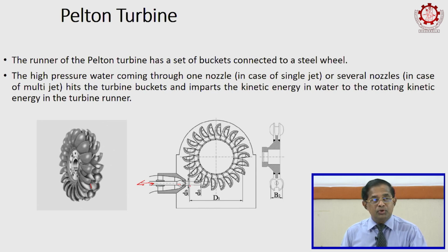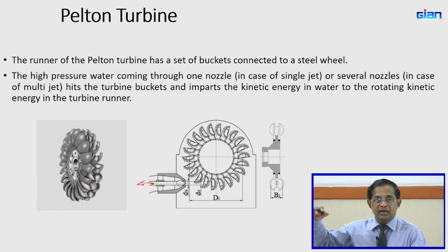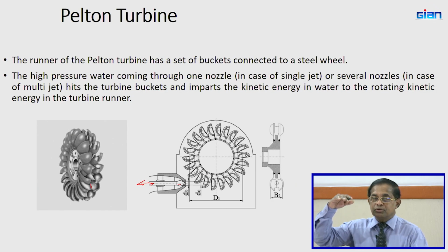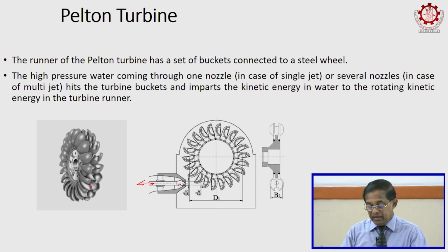That is how it works in a run of river scheme, which we will come to in a later discussion also. In a run of river scheme, the water coming into the project can vary slowly during the day. If rain comes, slowly the flow rate goes up, then the water level at the forebay tank tries to go up, which will be sensed, and the signal will be sent to the needle valve to open a little. Then again the water consumption or flow rate will increase, and thereby the forebay tank water level will come down. We will discuss that in a different place in detail.